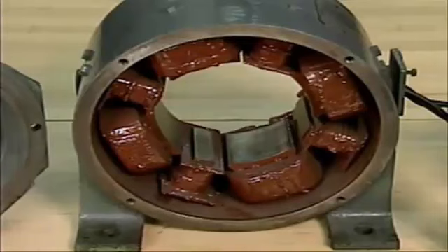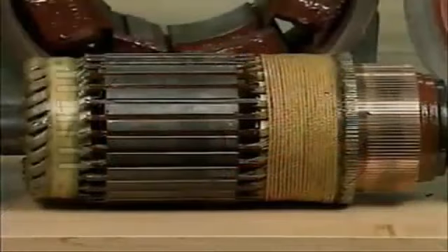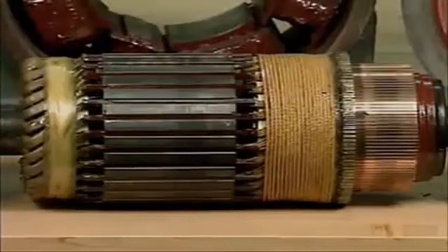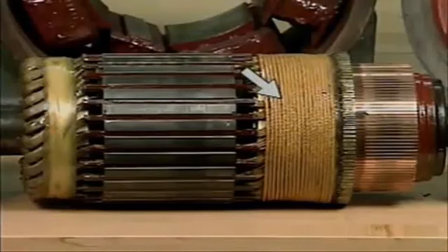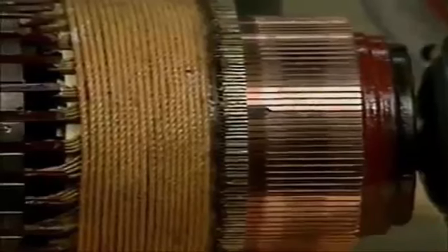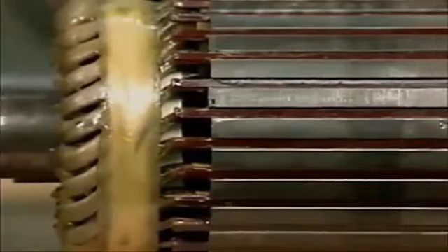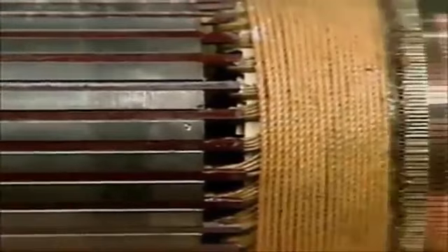The coils are electrically connected to a DC power source. The armature contains several loops of wire that are wound back and forth. All of the loops make an electrical connection to the motor's commutator segments. The electrical connections to the commutator segments are protected and held in place under a wrapping of varnish-coated fibers. Current flows from one commutator segment through the armature and back through another commutator segment.